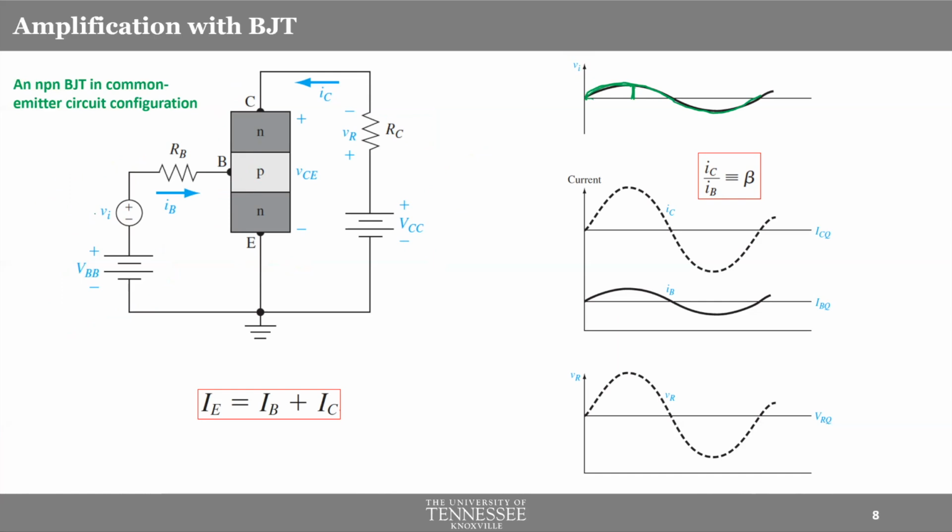Now this is the input voltage which we try to amplify. So imagine you have a voltage which has very low amplitude. Okay, say maybe 1 volt. You have 1 volt of amplitude in the input AC voltage. Now, this input VI will create an input current, input IB. If the voltage is sinusoidal, IB will also be sinusoidal. By the way, there will already be an IB which is corresponding to this voltage and this resistance.